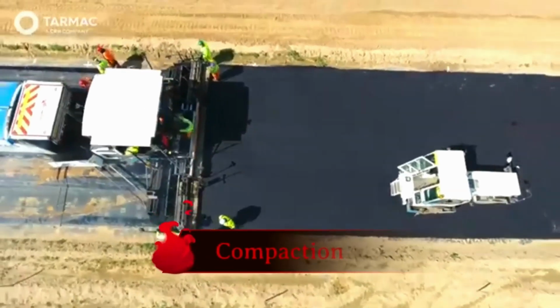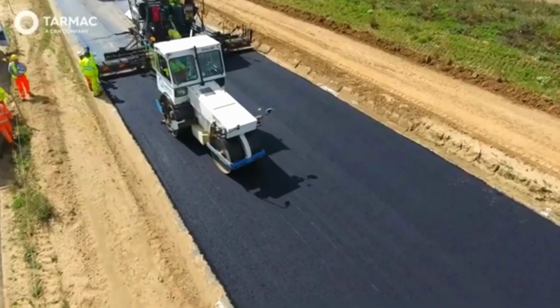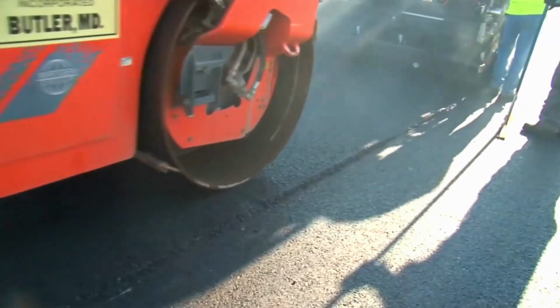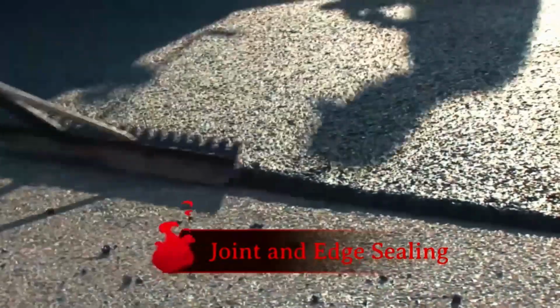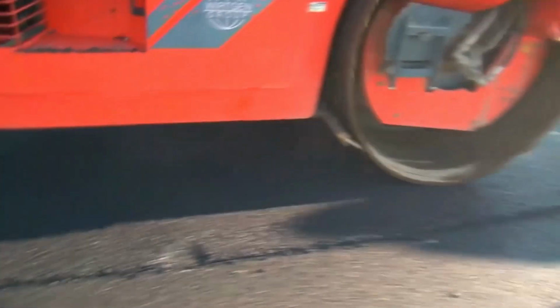Step 5. Compaction for strength and durability. Immediately after placement, the asphalt is compacted using rollers to achieve proper density and strength. Proper compaction ensures the overlay withstands traffic loads and environmental conditions. Step 6. Joint and edge sealing. To prevent water infiltration and edge deterioration, the overlay edges and joints are sealed using bituminous materials.